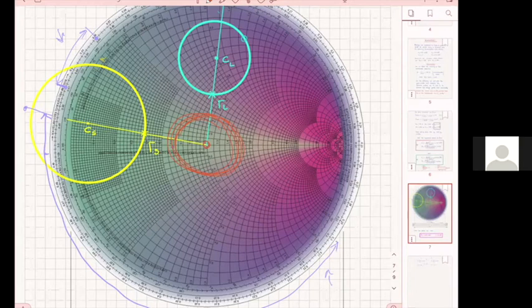It doesn't matter whether you are at 100 gigahertz or 1 gigahertz, it is relative. I always try to have shorter lengths, because if I have two matching networks that do the same job, one with shorter lengths and the other with longer lengths, my shorter length is going to have less frequency variation, and therefore is going to have higher bandwidth than my longer length.